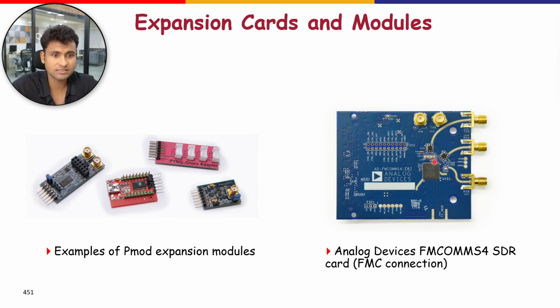So let's summarize what we have discussed in this video. We have introduced the various aspects of designing with Zynq MPSoC from a high level perspective. The composition of Zynq MPSoC and the roles of hardware and software components have been outlined, with appropriate links made to the device architecture. We have covered the design flow alternatives and tools available for creating Zynq MPSoC designs. Some practical information was also included on hardware software co-design, and we'll keep on discussing this later on. And lastly, we discussed the expansion cards and modules which are available from third-party vendors.